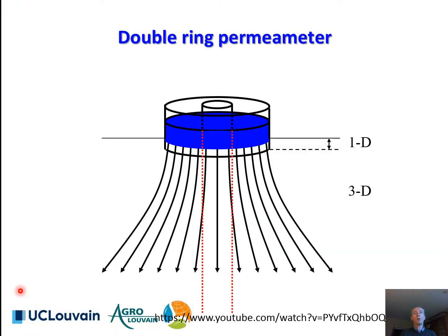One such popular measurement technique is the double ring infiltrometer technique. It is popular because it is rather simple to implement in practice. Have a look, for instance, at the demonstration shown in the YouTube film which is projected in the slide. It is a demonstration developed by the commercial company Ekelkamp.